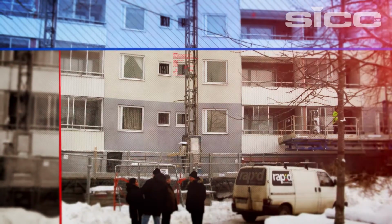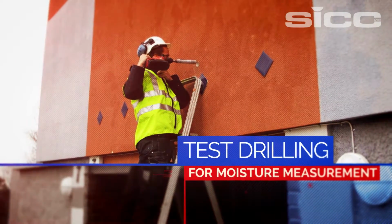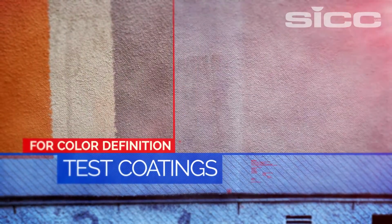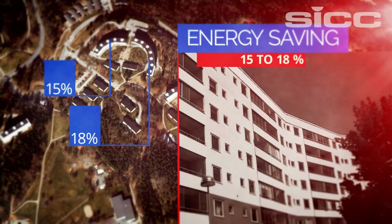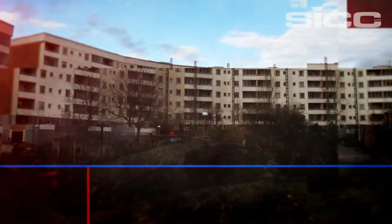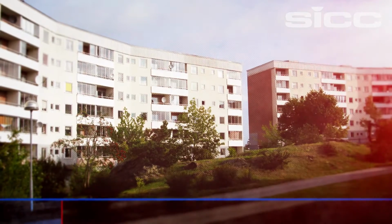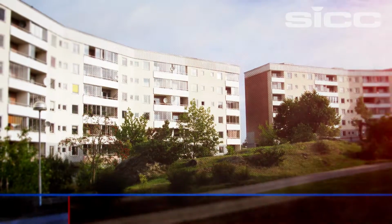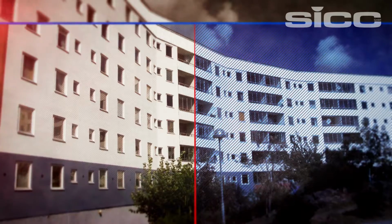Back in 2009, a project in the Swedish town of Botkyrka was guided by an independent institute. A thermoceramic membrane was applied as a wall paint to an existing facade. The measurements, which were produced by one of the largest energy advisors in Sweden, showed an energy saving of 15% and more in comparison to non-renovated facades. Here, big buildings are at stake, and that's why we may conclude that the results are representative as a result of low variance. We are talking about just a 0.3 millimeter ceramic coating, which has been applied to the facade.